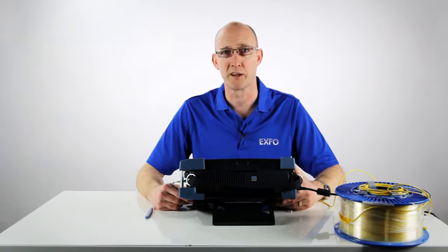The 5700 is a fully automated CD and PMD tester based upon international standards. It's suitable for testing all types of single-mode fiber, has a dynamic range good enough for metro, core and long-haul testing. Additionally, its accuracy means it's suitable for 10, 40 gig and 100 gig certification. Let me show you how it works.